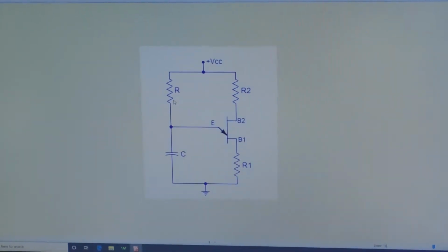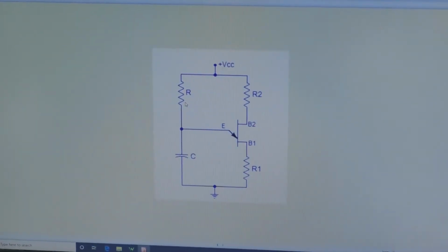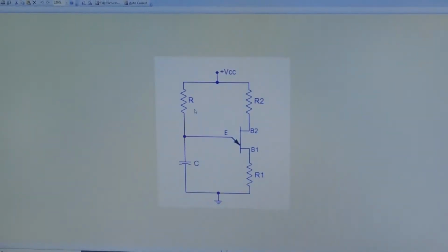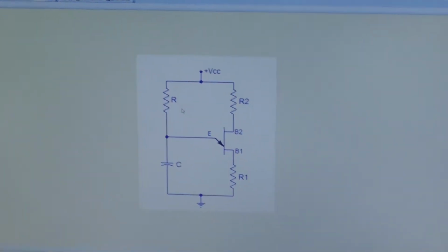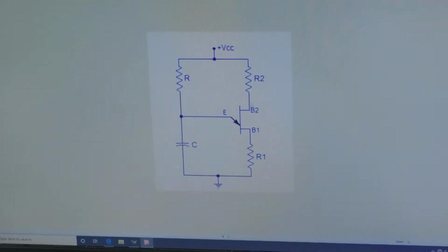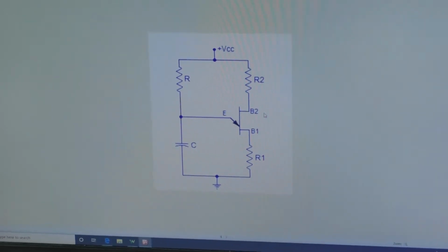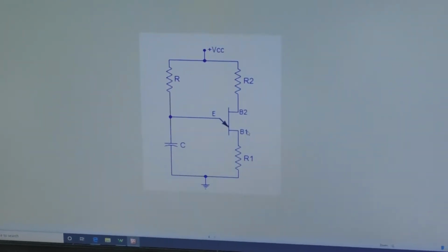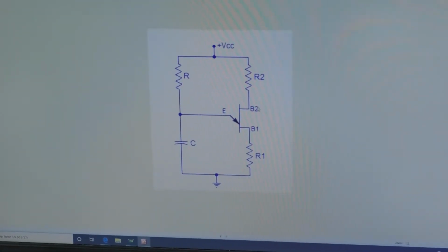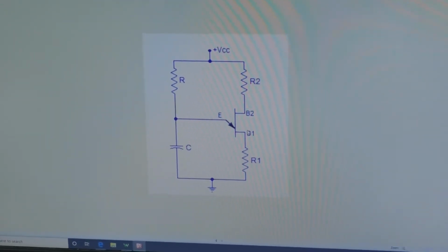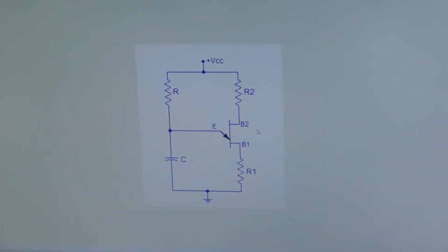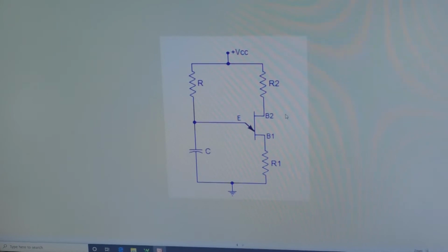If you see the circuit diagram, the UJT relaxation oscillator is a type of RC (resistor capacitor) oscillator where the active element is a UJT, that is nothing but a unijunction transistor. A unijunction transistor is an excellent switch with switching times in the order of nanoseconds. It has a negative resistance region in the characteristics and it can be easily employed in a relaxation oscillator.